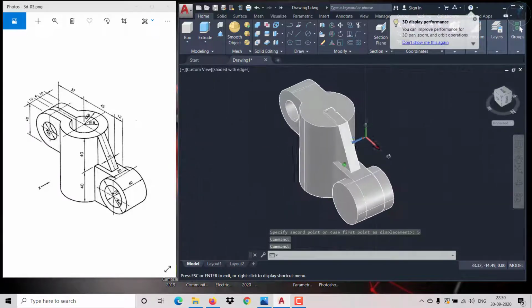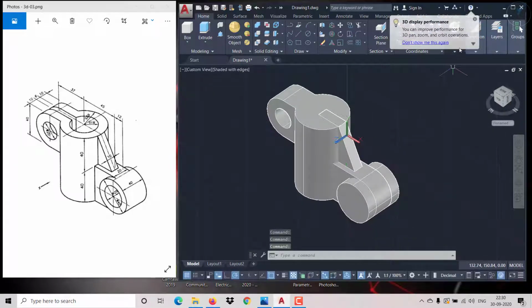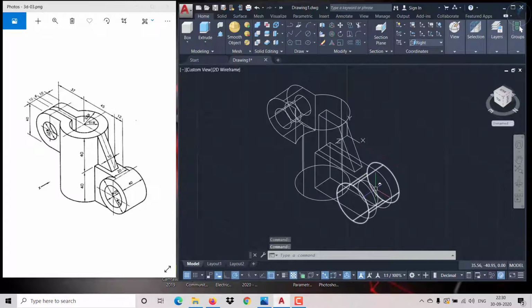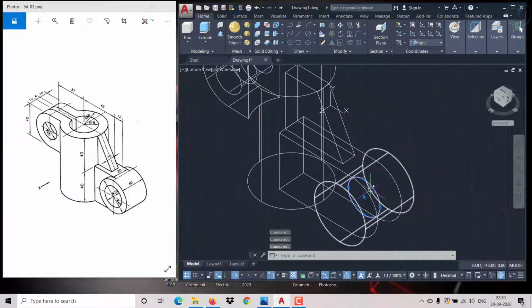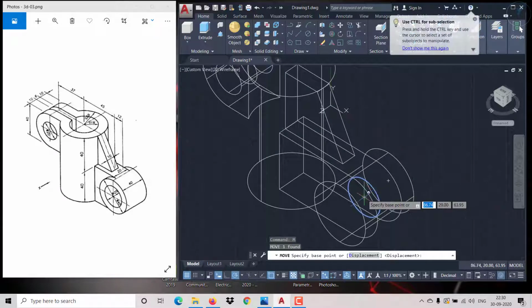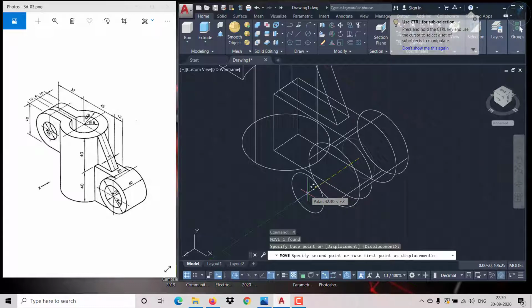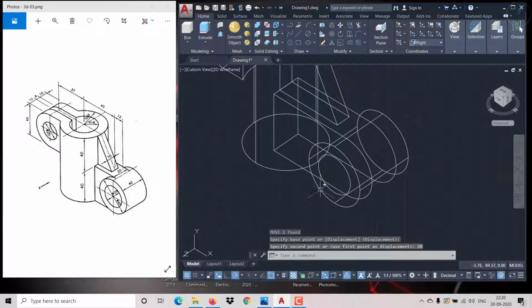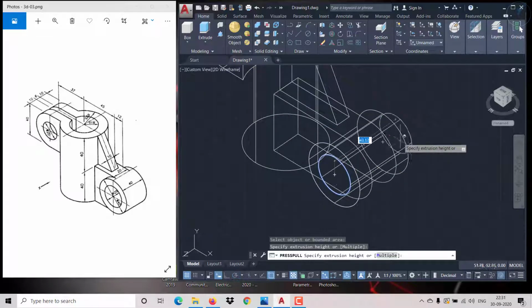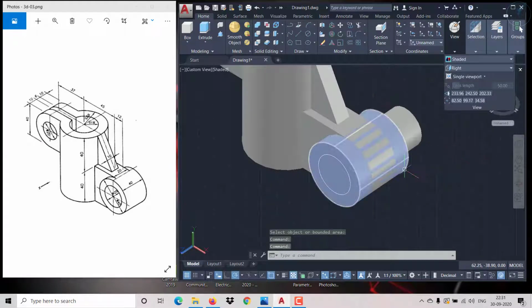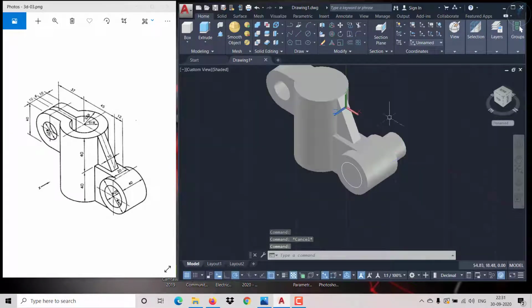So now we need to create, I think before that we can make that hole, because in this way we can't see it, it is inside. So make the hole move outside of 20 mm, so then only it will come on the top surface of that cylinder. So now from here you can go press pull, click on that, inside. It will form you a solid, so later we can subtract it. Before that we need to add all those things.